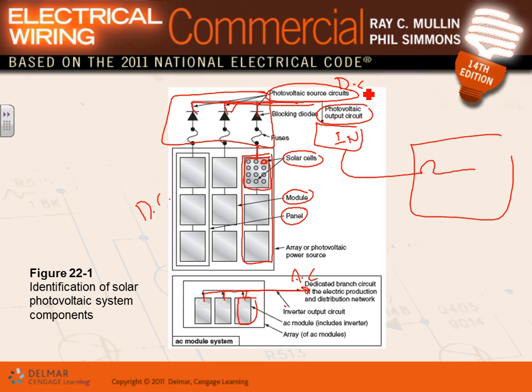I can't emphasize this enough. We start with the cells, but multiple cells in series, guys, get you a certain voltage, say 24 volt. Get multiple 24 volts together, it gets you 48, or keep adding all these modules together, whatever voltage. And each one of these cells, say 200 watt at 24 volt. So the more panels you add, say 10 panels, I'll give you 2000 watt. You need another 10 panels, I'll give you another 2000 watt. Here's a 4000 watt. Does that make sense, guys?